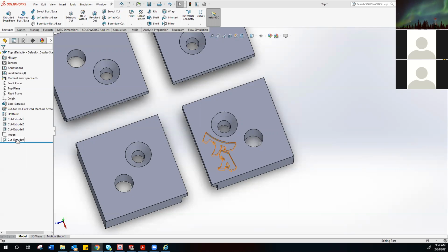Children, the rest of you. What you need to do, because I'm not going to get back there, because it's going to take me a while to fix this, 3D elements. You then need to go into, we're on the top plane right now. You need to now start a new sketch on the front plane and draw a center line axis from 0, 0, 0 straight up. Yeah, just straight up the axis.